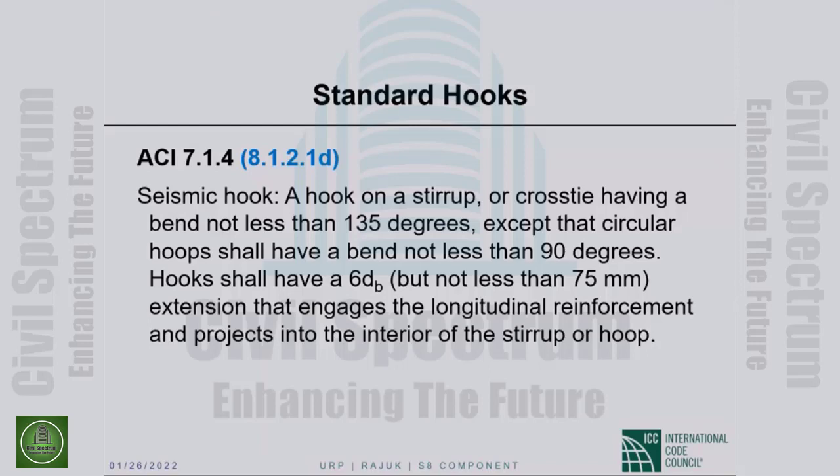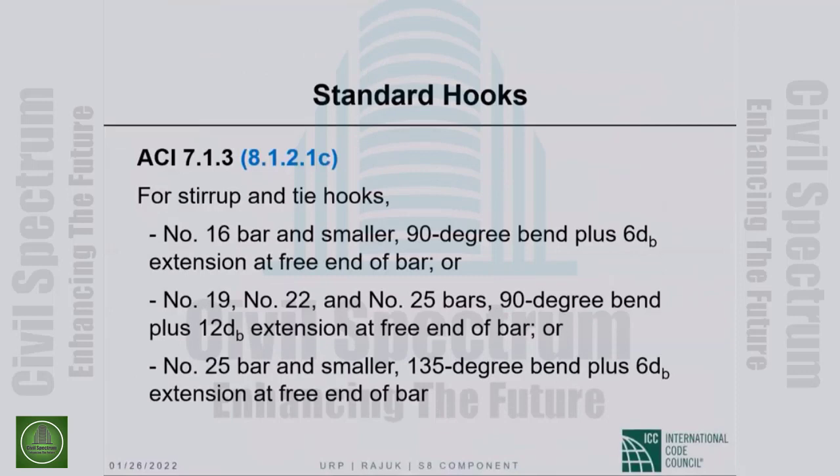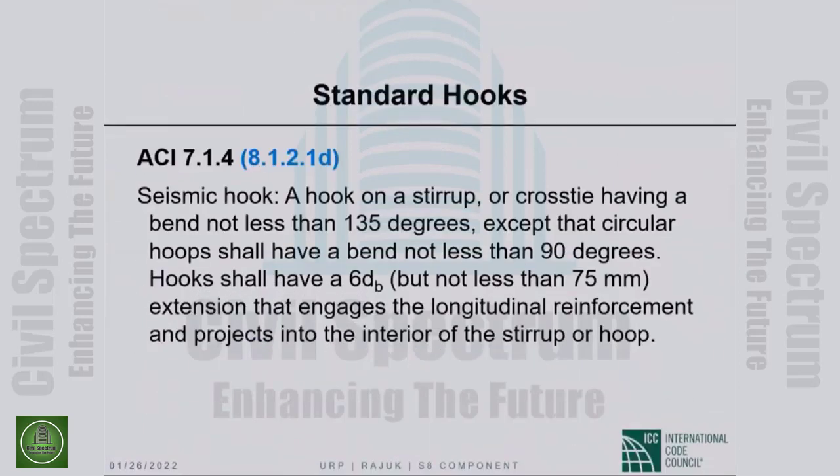So the main thing I should have pointed out is, standard hook on longitudinal bars, standard hook on stirrups and ties. Okay, somewhat different. Now we are talking about seismic hook. A seismic hook is a standard hook, but it's a special standard hook.